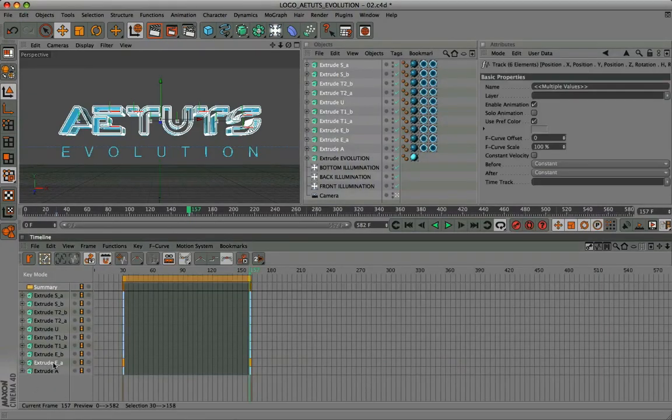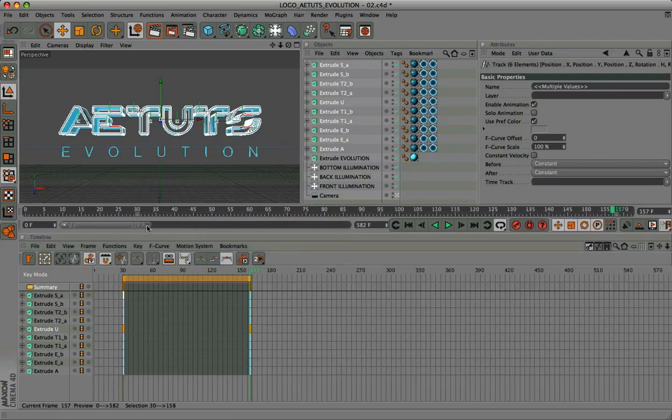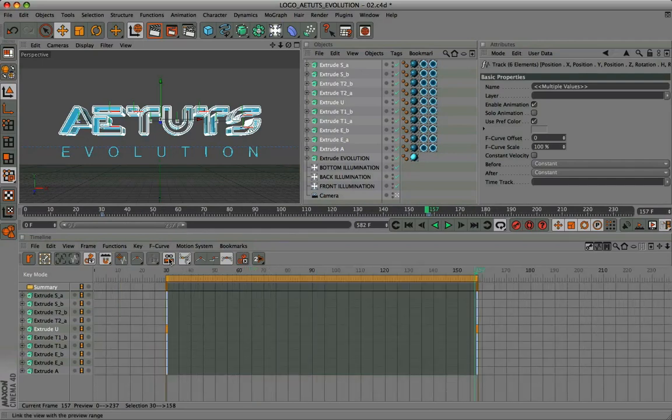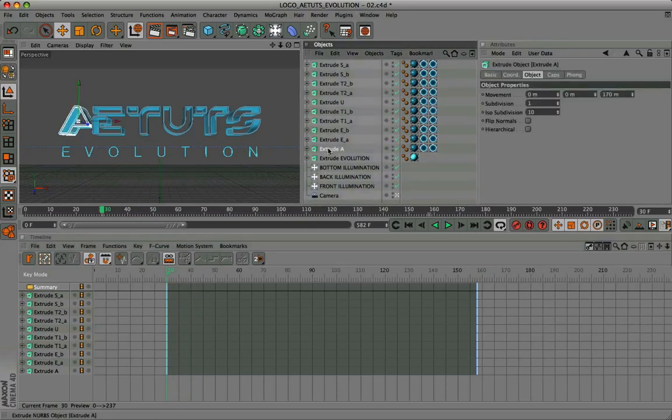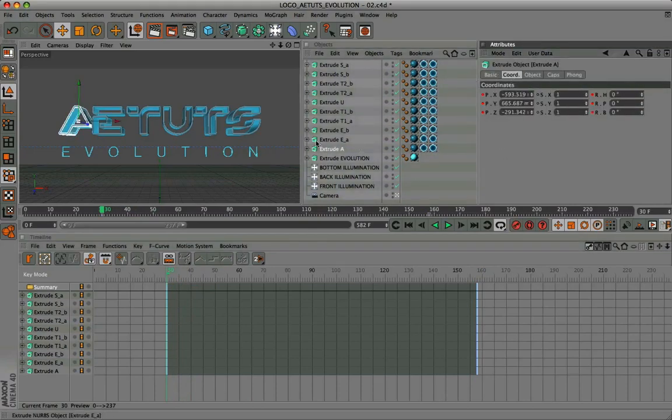This will allow us, through the animation panel, to make changes on every letter, as you can work directly on this panel. We are going to change only the parameters of position and rotation associated with frame 30. This way you can work very quickly. Extrude, to begin work on the A letter, we will modify the parameters according to the scheme proposed by me.